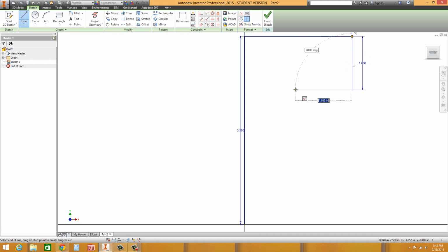So just click, get this over here somewhere, make sure it's 90 degrees, click, drag it down. Next one as well, we'll just click, because I have a baseline dimension, I don't know the exact dimension. I think it is actually 0.75. But then align yourself to this edge, click, drag it down. Click here, drag it down. This one goes in a little bit deeper, click. Then attach it to this bottom edge of the crosshairs, click, and connect it to the origin. When you get the green dot, click, and now hit escape on your keyboard.